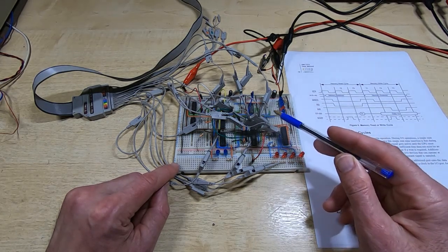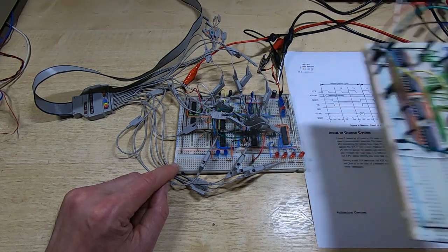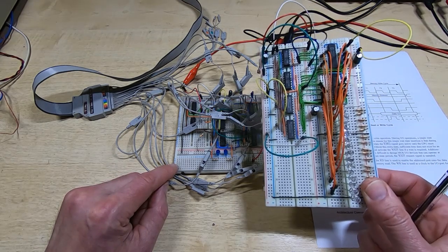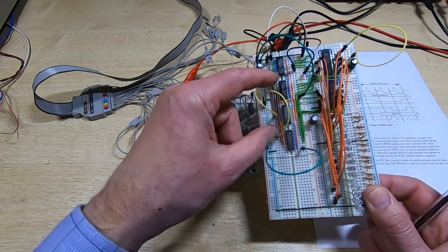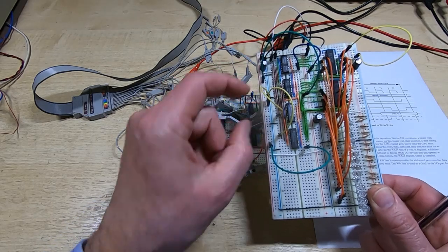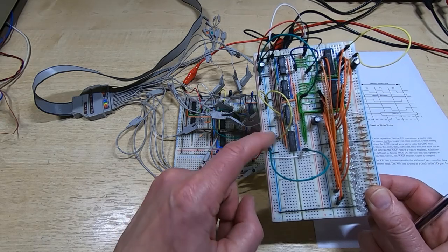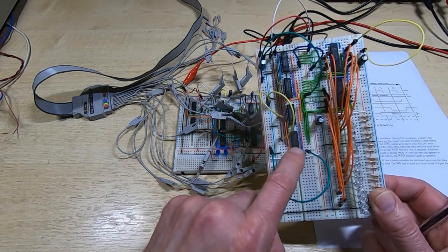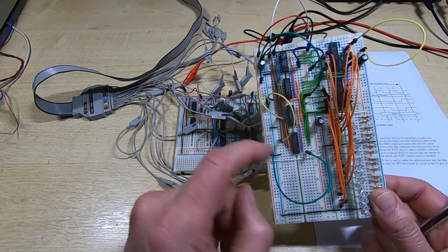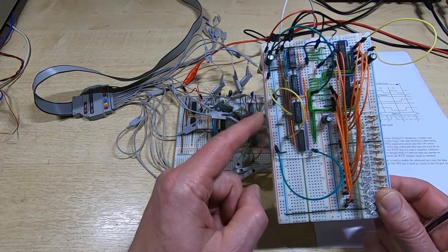It also controls the counter, so that's a 16-bit address counter, because we need to be able to load this using 2 in-out cycles, because we're loading it with 2 8-bit values, 16-bit counter of course, for the address bus. But these are 74 LS161s, and to load them we need to apply the required data values to the inputs.